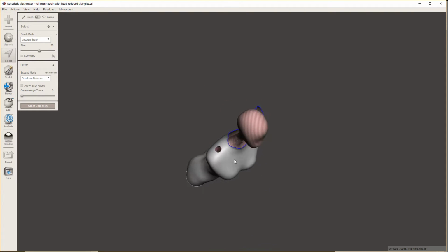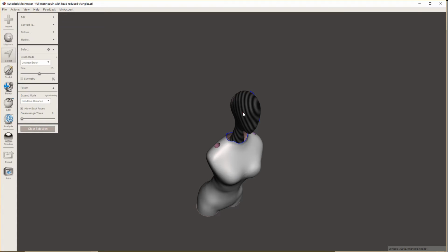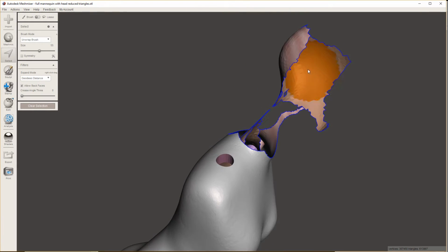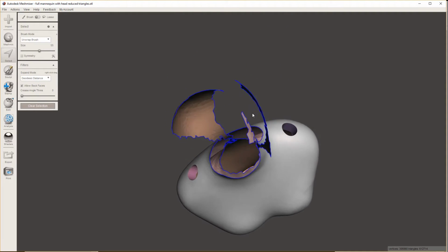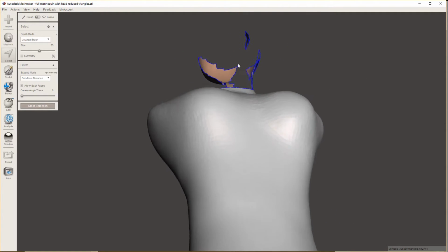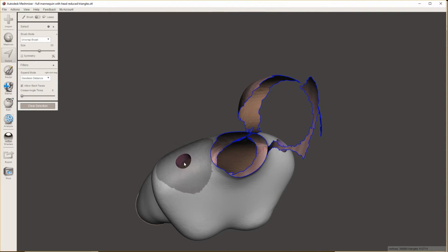We can see that we have an inner head, and going down, I can turn on allow back faces here and kind of paint on the head here. Delete that. Kind of looks not too nice. Let me make it a little bit nicer. But we can see that the inside of this is completely hollow. So that is kind of a little crash course on hollowing, but this model hollows just perfectly to allow for resin to drain out or whatever. You could put the holes on top of the head or whatever you want.